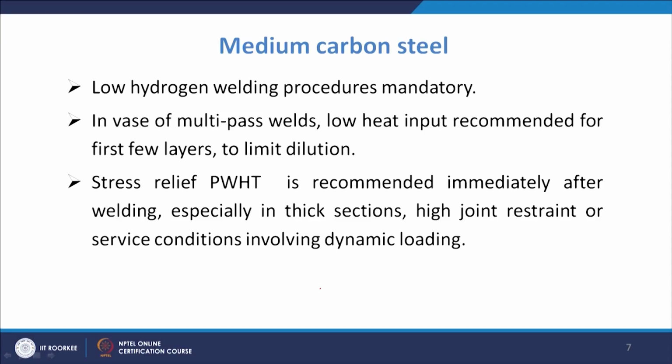What it does is that it also promotes the diffusion of hydrogen from the weld zone, and consequently it will reduce the crack formation tendency, or any undesirable microstructure which may result because of the other parameters. So, that is what should be followed in the case of medium carbon steel.